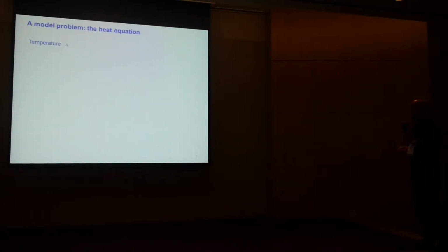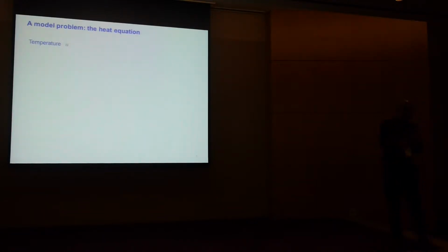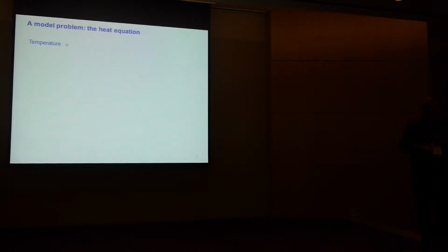All right, so to take one step back and set the scene, let me run very quickly through a simple problem, which I'm sure we're all familiar with, namely the heat equation. I have a single scalar-valued variable, temperature. We have a balance equation or conservation equation, in this case balance of energy, in which we see the heat flux vector q, and on the right-hand side, a heat source term.